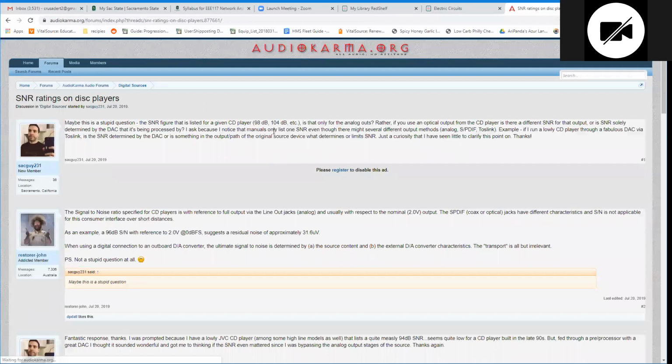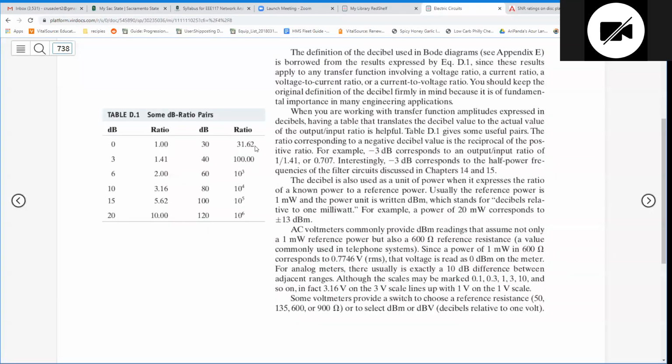It's around 98 to 100 dB for a CD player. 100 dB is 10 to the 5th. That means if we have 100 volts input, we're getting 0.01 volt noise. That's nothing. You're not going to hear it. The human ear probably can't even hear that small of a noise difference. So 100 dB is crystal clear, and unless humans make their ears magically better through evolution, we're not going to need more than CD players.